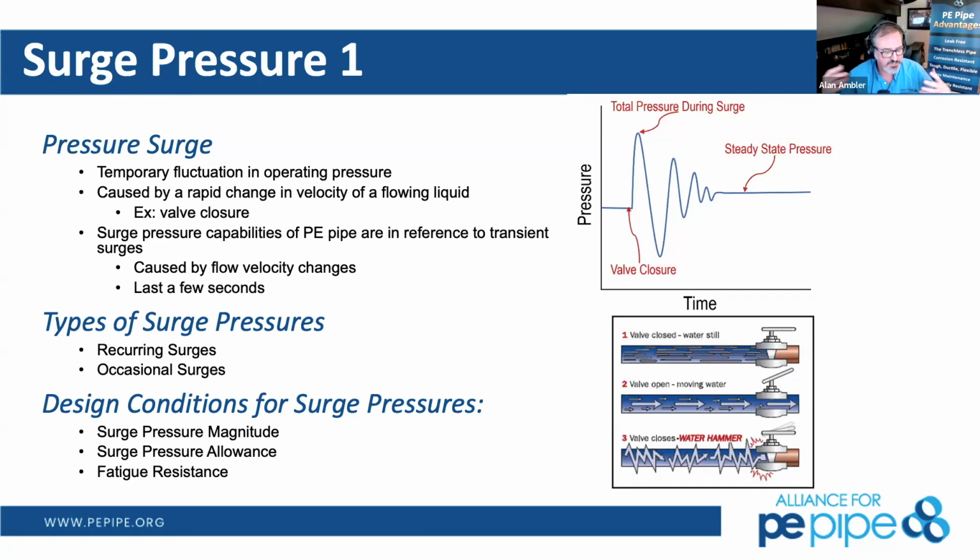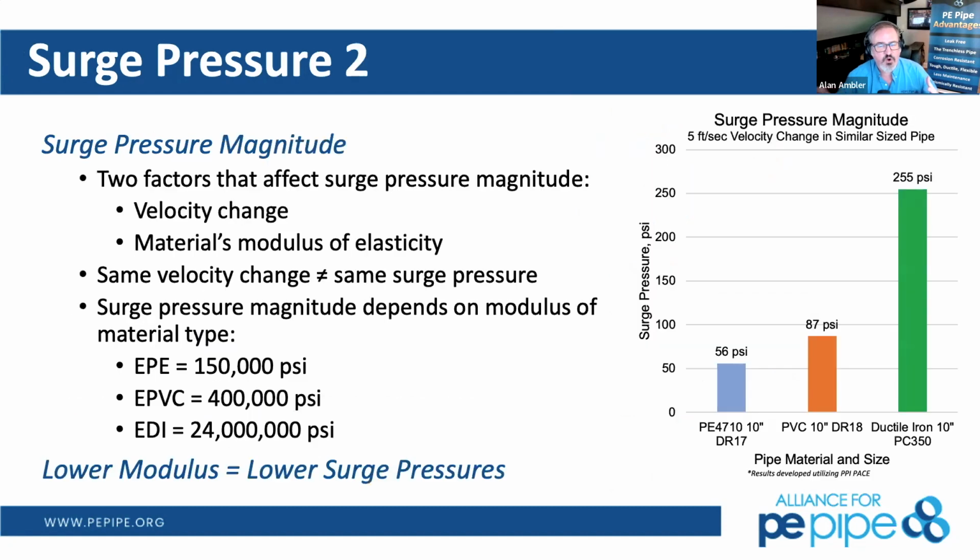If you have variable speed drive pumps, those obviously mitigate that surge a little bit as well. Or if you close the valve, open the valve, maybe too quickly, that type of thing. So you'll see water hammer that occurs within the pipe. It'll also represent an increased surge through it. We want to make sure that over time, that change in surge and water velocity is absorbed within the pipe, so it doesn't lead to fatigue.